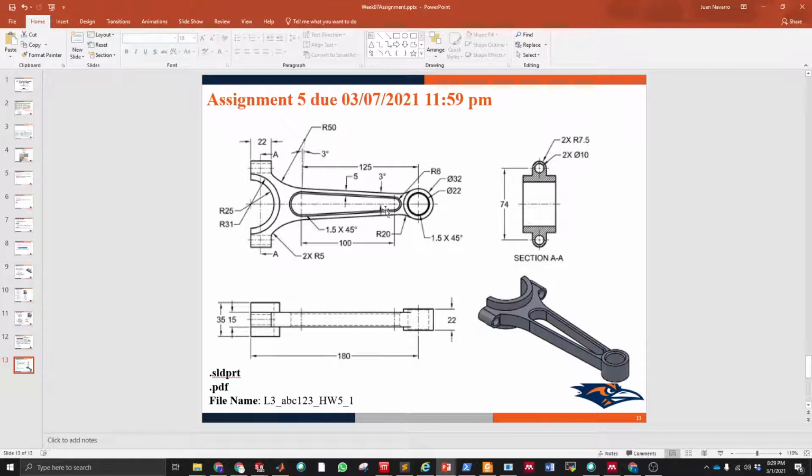We have this section view for this point here, highlighting the fact that this part here has these arcs, these circular holes. Also, we have chamfers coming through this loop, 1.5 millimeters at 45 degrees chamfers at both sides, in the top and in the bottom.